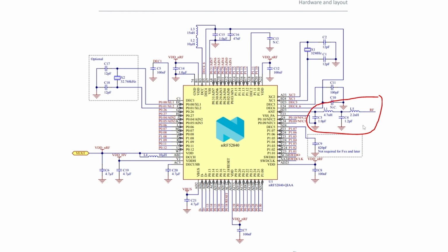Now, for these types of things, it's not only the antenna and your impedance matching that you need to worry about. There's a lot of things you need to keep in mind. I've made a separate video on RF design guidelines, but to encompass it overall, you need to have a 50 ohm track as we are working within that, and I've always routed a 50 ohm track for RF stuff. You need to be quite aware of where your ground planes and ground ports are. You need to be aware of where other signals are traveling. Do you have something going under? Do you have a critical path next to it? Do you have a critical component next to it? These are the things to be aware of, and I'll plug that video in the description. But it's not only impedance matching you need to worry about to get your things to work.